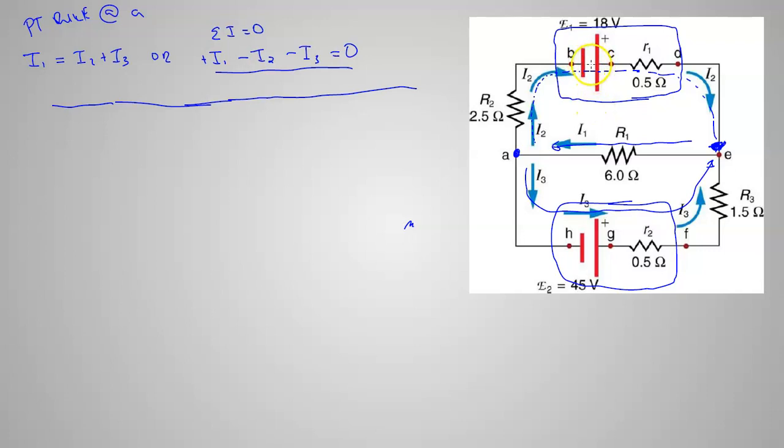But you see how the battery is this way, and the current is going from positive around to negative? If you can make these arrows match the direction of current, that makes it easier to set up all of your signs and to get it right. You can do it the other way, but if you follow the current as much as possible, it just makes life easier. Okay? So when I think about a loop, I'm going to try to follow the current too, and maybe I start right here, and I go around following I2, and then I'll come back I1 like that.